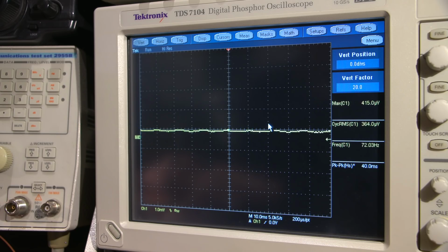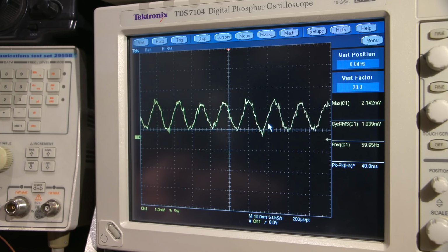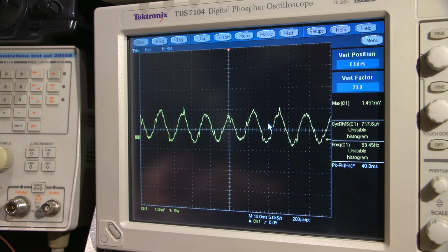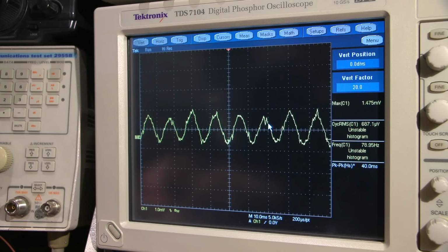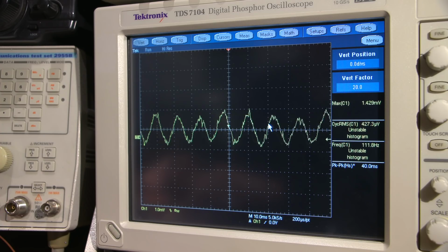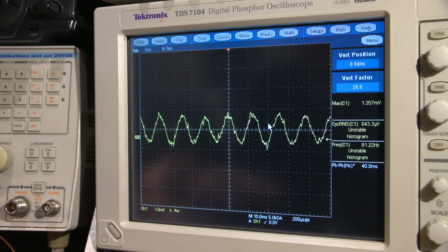That's really how simple it is to verify that that stage is working. When you're troubleshooting, that's all you're looking for, just a rise in amplitude. So I'll go here again, and as you can see on the collector, test point number 3, we have amplitude. Just that simple. So we verified one transistor is working already.